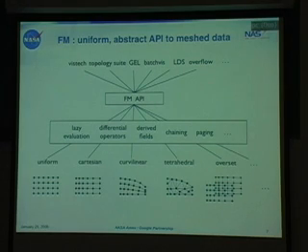And along the way, we can run the values through various filters. For example, differential operators, we might want the gradient of some scalar quantity or the curl of a vector quantity and so forth. And the really nice thing about this is that it is able to provide the same API for a number of underlying mesh types. And we see a lot of different kinds of mesh types. In the example I showed, it's overset curvilinear meshes. It's a whole bunch of curvilinear meshes filling space, but we might see tetrahedral meshes, which are unstructured, and various other kinds of discretization schemes.